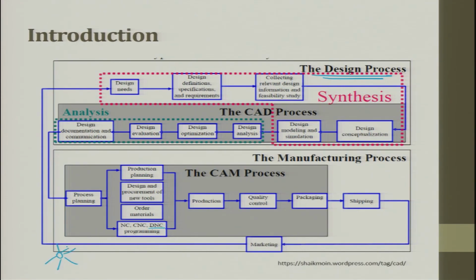Every time, the information is pulled from the server and then executed in the CNC machines. If you have a long program it is done at once, and if it goes line by line or segment by segment, then it is called drip numerical control. But what we are talking about here is direct numerical control.